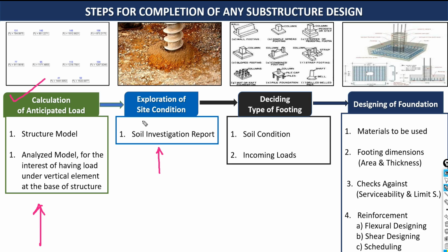Okay, so we'll see how to read this report. And then third, after having these two things, loading and capacity, we need to decide the type of footing. As we have learned, there are so many types of foundation: isolated foundation, stepped foundation, sloped footing, raft foundation, pile foundation, strap footing, combined footing.